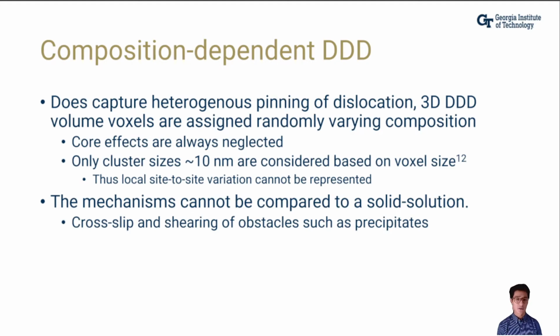The volume voxel resolution employed is on the order of tens of nanometers. Thus, it's more similar to describing dislocation interactions at large obstacles. A multi-scale method, then, that accurately represents discrete solute fluctuations and is able to reduce the degrees of freedom without sacrificing accuracy has not previously been demonstrated.